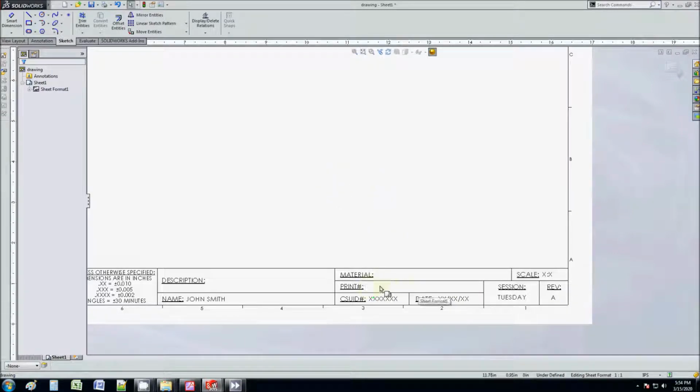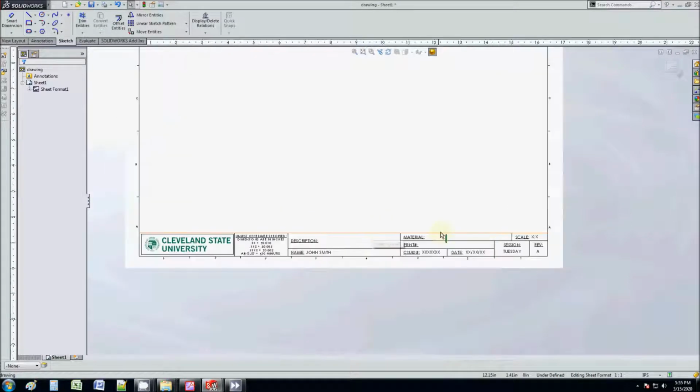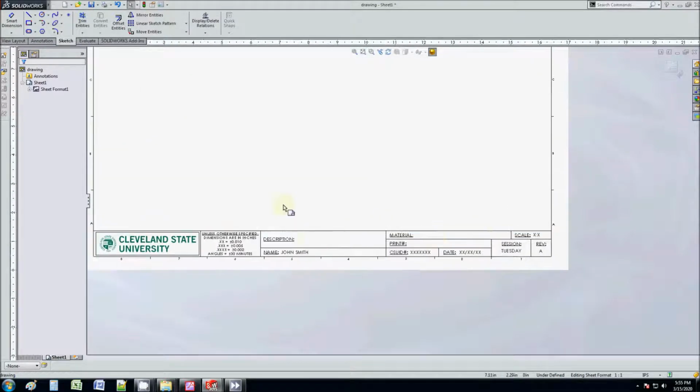Print number nomenclature, I've seen that vary between projects. Usually there's like a project number, then assembly number dash print number. That kind of varies, but just make sure it's consistent and it's self-intuitive. Okay, it's consistent, it's intuitive, and it makes sense. So those are some of the more important items of a template.